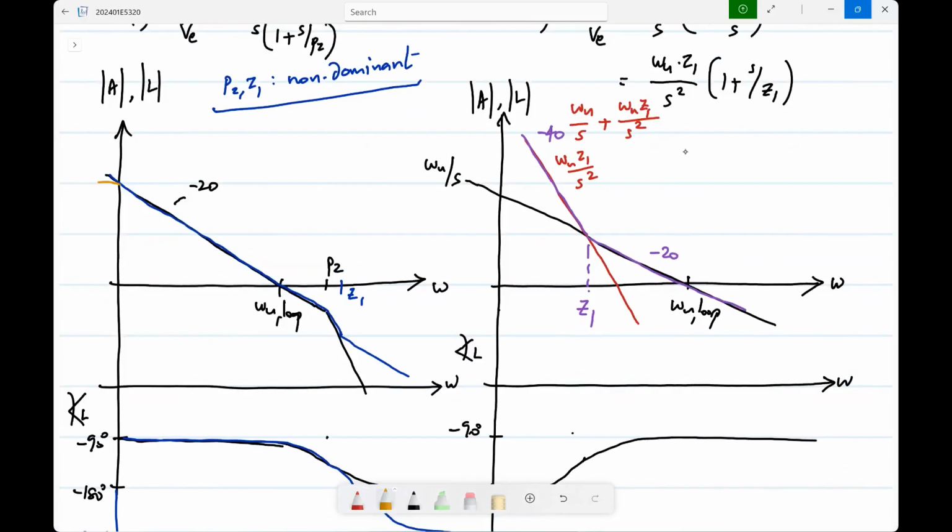So let's say this is the DC gain value. It will get limited to that. So as you go to lower frequencies, both these curves are showing that the op-amp's transfer function is going off to infinity. It won't go to infinity, it will flatten out at the DC gain, whatever the DC gain is. If I assume the same DC gain for the two, this will flatten out like that.